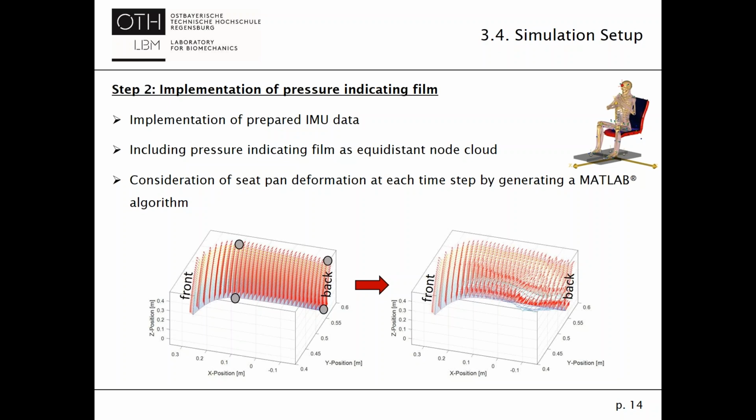According to the human who is placed by using markers, we know the penetration of the rigid chair surface. So now we can generate a linear relation between the highest penetration and the highest pressure. But the deformation is not in global coordinates, as the seat lies anyhow in space. So therefore we pick vertices on the seat pan. Those are marked as gray spheres in this figure here.